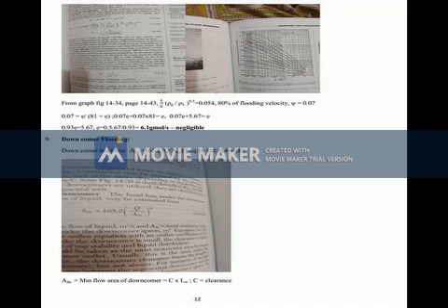If you convert it into millimeter of water, and then convert it into Pascal, it is coming around 817, very small. That is 0.817 kilopascal. Our atmospheric pressure is 1 into 10 raised to 5, so it is very, very negligible.